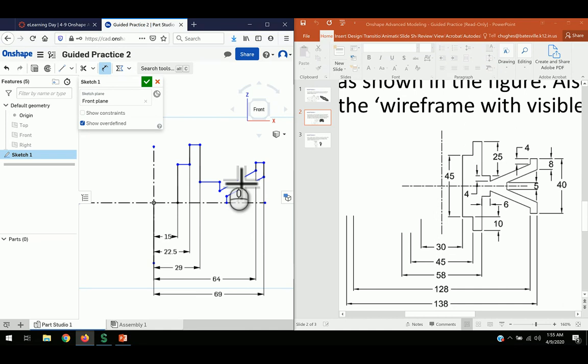And that will kind of help out there. All right, so still some blue lines, means we got a little bit of work to do, some dimensions. So that's some of these interior dimensions here. If I start kind of from the left to right here, from the top to the other side, if I use the center line, this is going to end up being 20, since that says 40 tall.